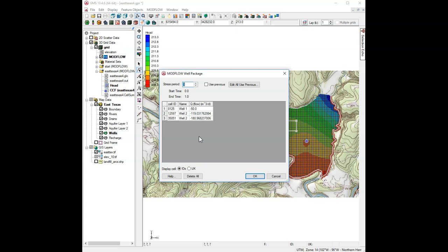Ideally, what you do is you run the model, and the amount of water that's partitioned that comes from each layer should be a function of the heads and the pressures in each layer. And you really don't know how it's partitioned until you actually run the model. For this reason, they developed some subsequent well packages in MODFLOW called multi-node well, MNW, and there are some different versions of that.